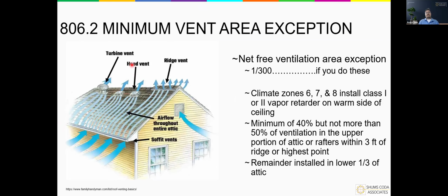So here's really what's happening there when we talk about this. We see that soffit ventilation come through, we get airflow through the attic, and then passing out through our vents. We have slant back vents over here. We have ridge vent, right? Now, some of these are not meant to work in concert with each other, and that's an important thing to note. A lot of manufacturers will tell you, pick one and stick with it because we can create instances of short cycling and create even intakes in the wrong places. Going back to that question we had earlier about getting some airflow in there and then getting some moisture buildup as well.